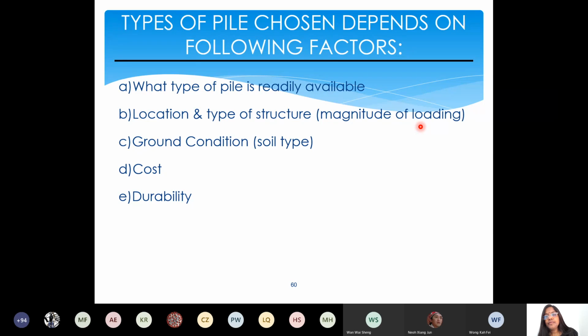Again, you follow the code book. In the code book, the type 1, 2, 3 methods are there. You need to adopt exactly the required type of wind. And then, because the lateral movement is not only downward, the force is acting laterally, wind load. Okay, next, last one, earthquake. 4 types. Remember these 4 types. Assume that in all your designs you have these 4 types of loading: dead load, live load, wind load, earthquake load. All these 4 you need to analyze for any high-rise building for sure.